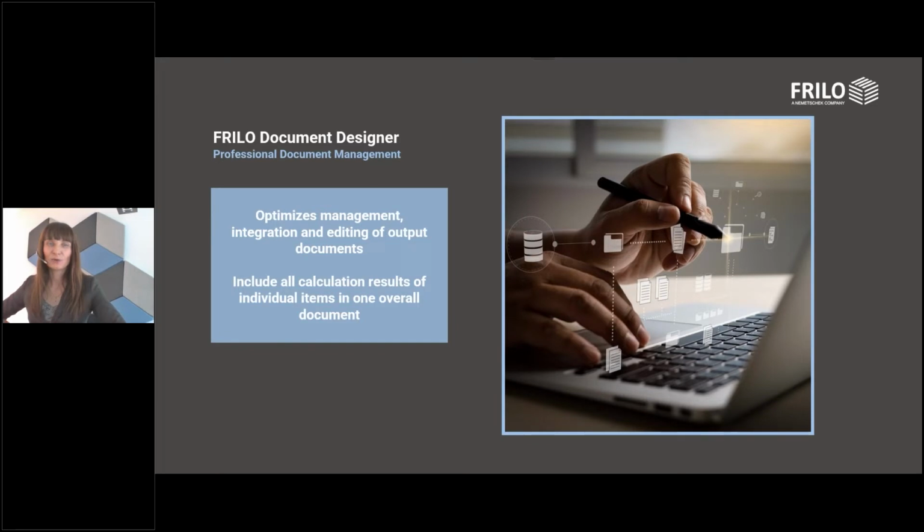FRILO Document Designer also deserves a couple of words because it is a very professional and comprehensive solution for document management that is integrated into the FRILO application environment. Here you can compose, you can create overall output documents containing the results out of different items calculated in FRILO. For instance, if you have a building that consists of a beam, a slab, a column, you can calculate all of those building components in separate programs and then store the results within one project and then create one overall document related to this project containing structured results with regard to different items that you have calculated for this project.